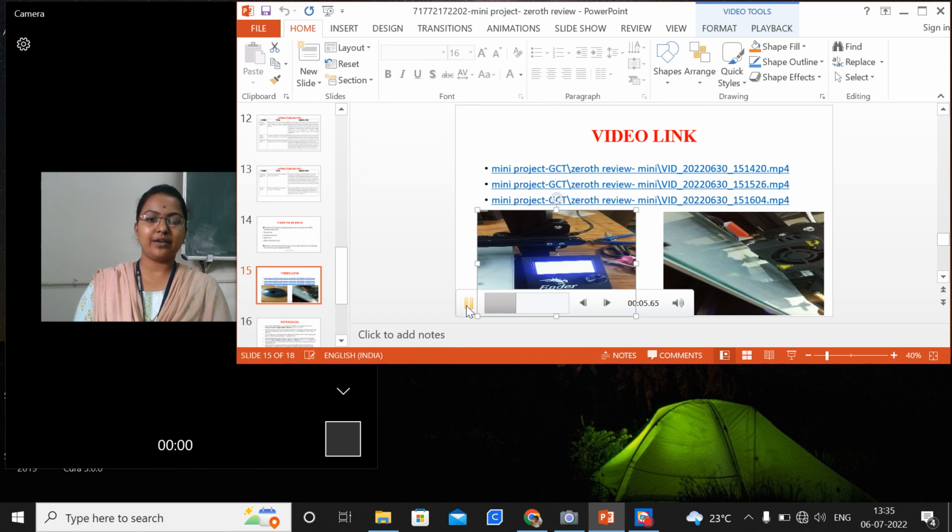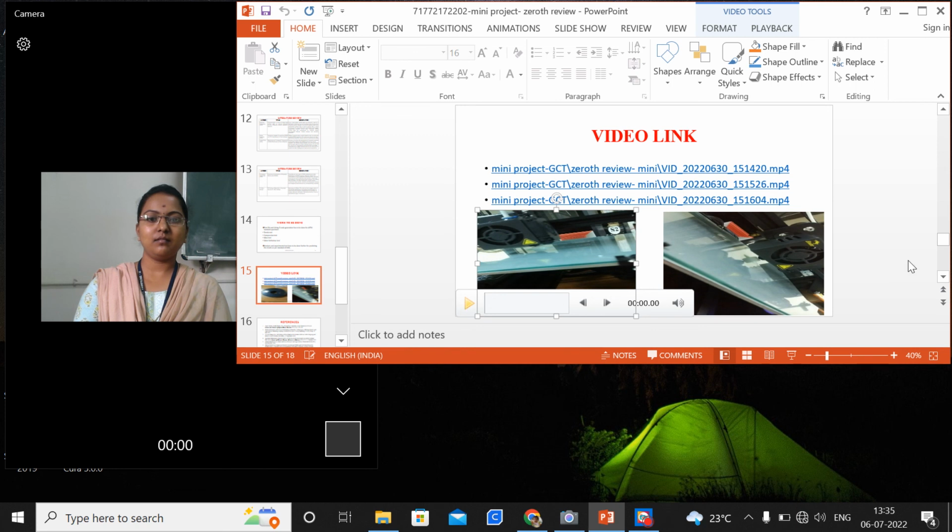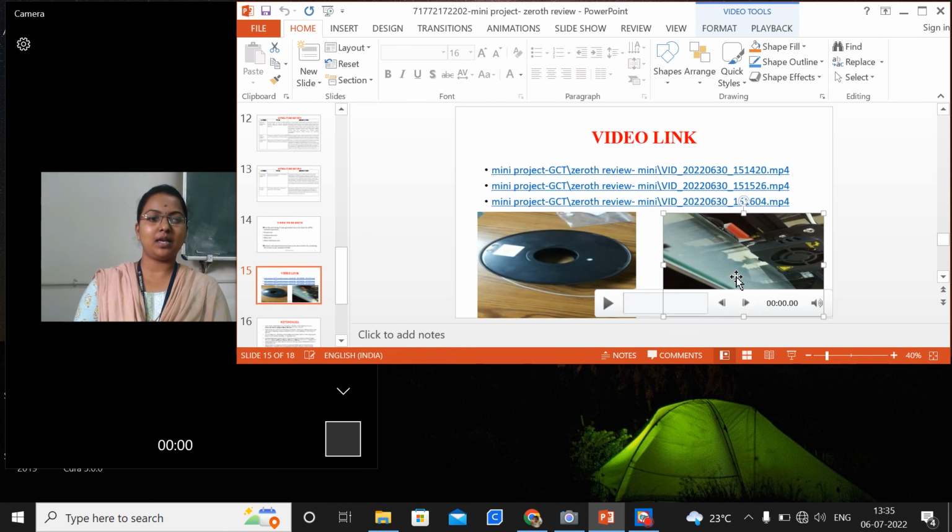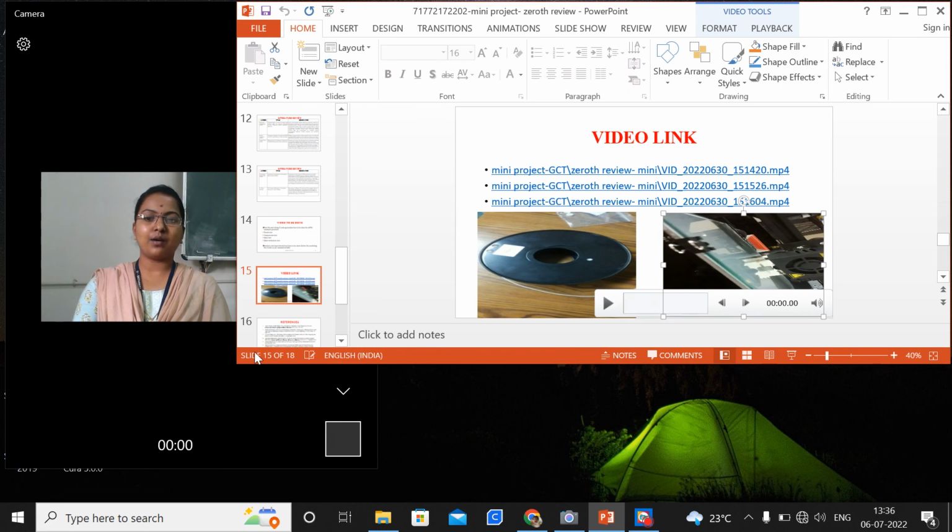This is an FDM printer with a display monitor. The extruder will be loaded with the PMMA material to produce a tooth-like structure. This shows how the material is taken up to the extruder, and how the heating nozzle and the bed temperature need to be maintained. After that it forms the particular component.